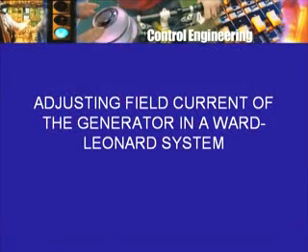But we are looking at the other type or technique, namely armature controlled DC motor. That is, the applied voltage will be changed. Now for change in applied voltage, we can do what the operator was doing, namely a resistance in series with the armature was being adjusted by the operator. So we could have that operation done automatically, or we can go back to the Ward-Leonard system where the applied voltage EA was being produced by a motor generator set and the applied voltage was adjusted by adjusting the field current of the generator.